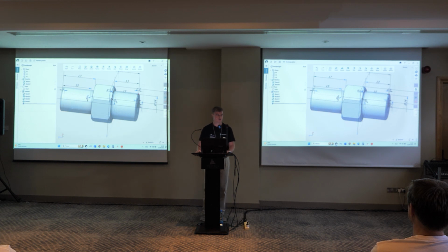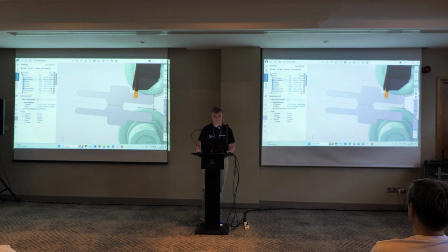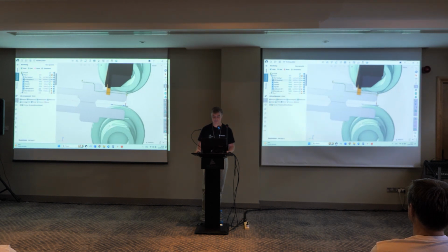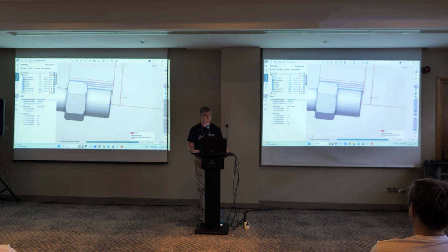And after that, I can go to machining. For the turning operation, I need to touch job assignment, and if I draw it, the profile was updated. After that, I can recalculate the toolpath, and we will get the simulation for the part with new dimensions.